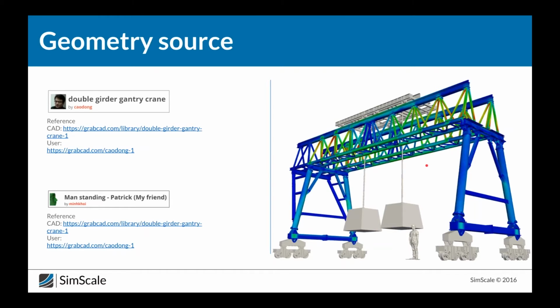The other thing that is of interest with this structure is the way the ends are supported. The ends are almost identical, except that the far end here has a diagonal brace, which makes this end rigid, whereas the close end here is pin jointed at the top.